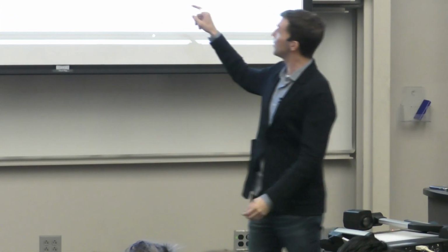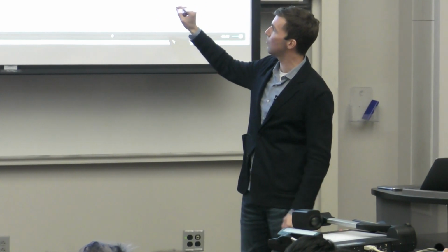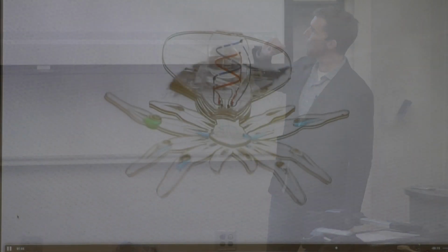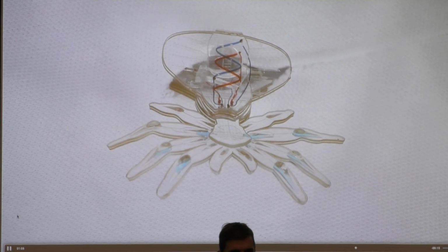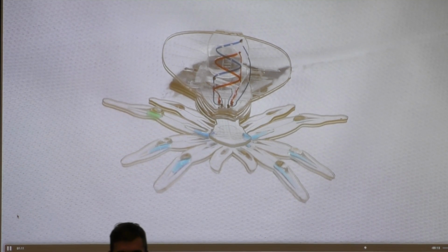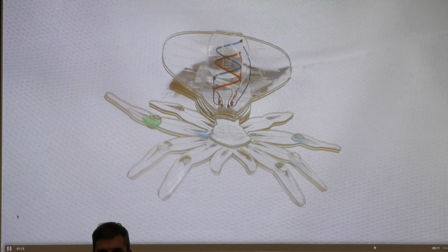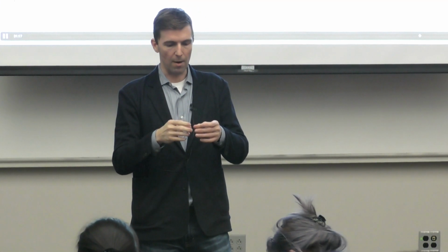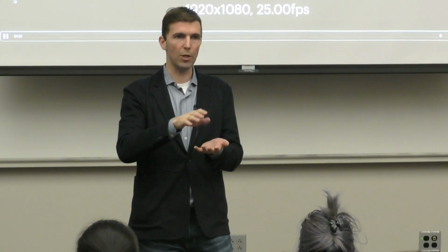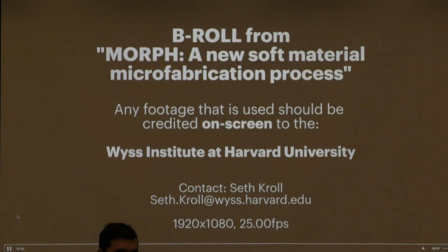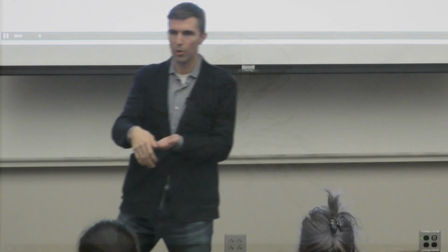The other thing I want to point out, which I think is really cool about this process, and which was kind of hard to see, is that I can create actuators in these multilayer soft lithography microfluidic networks, and they're very simple. I basically have an unpatterned side and a patterned side with a gap in it, and if I pressurize that gap, it bends towards the other side. So a very, very simple actuation architecture.